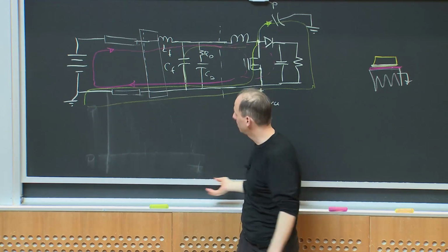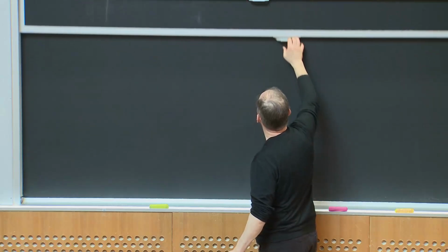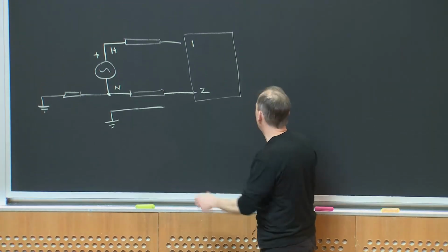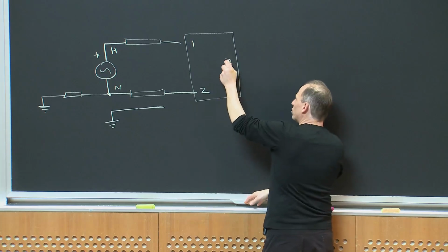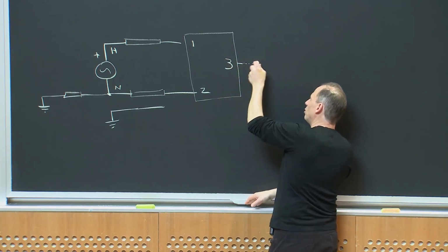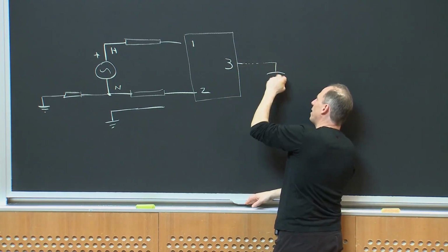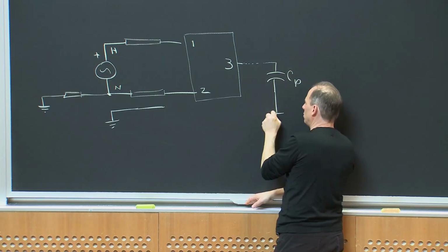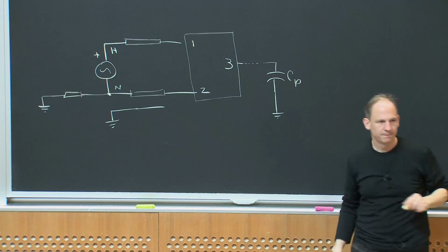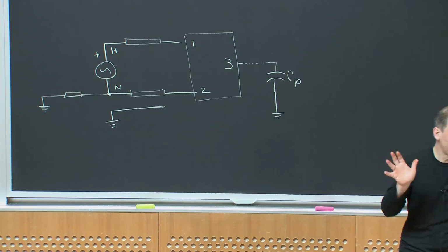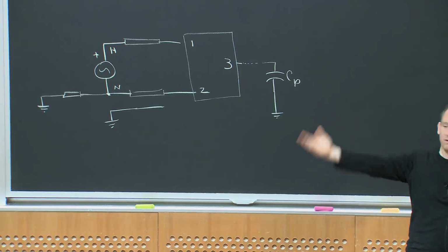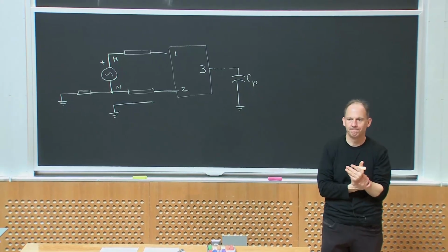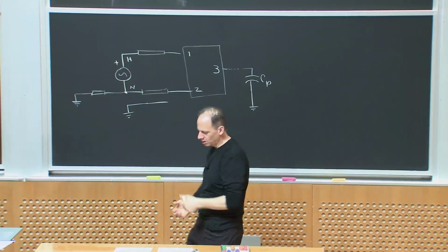that my converter then processes. Okay? So the consequence of that is even though I don't intend it to be there, right, there's going to be some virtual third terminal which is connected by some parasitic capacitance again back to ground. Okay? Even if the case isn't connected to ground, ground is around you, right? There's going to be some flow possibly through that. Okay? Any questions about that?